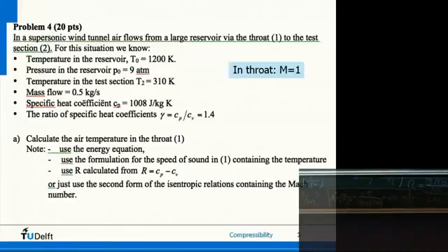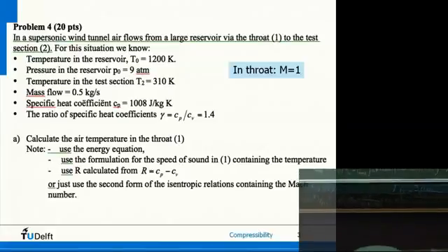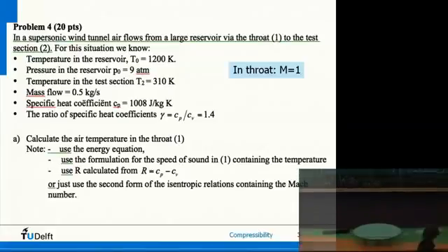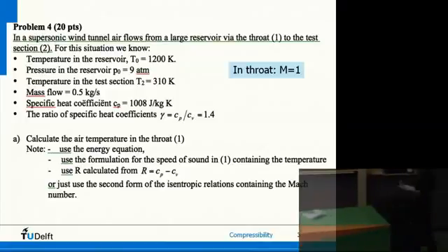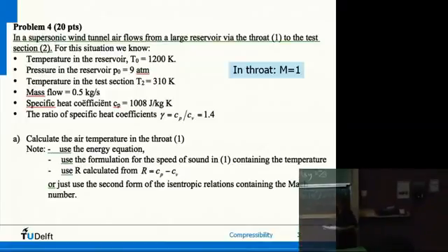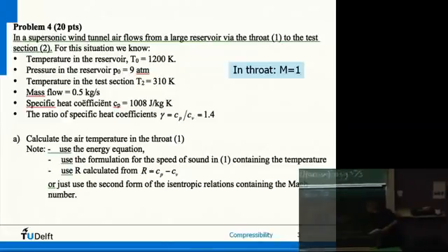If you look at our hypersonic wind tunnel, we have a wind tunnel where we can obtain a speed in the test section of Mach 11. We have a very strong contraction ratio. Also the flow expands very strongly, and then the flow compensates, so we can only measure for 1 millisecond. Yeah, is this clear? Any questions about this? So maybe for some people.